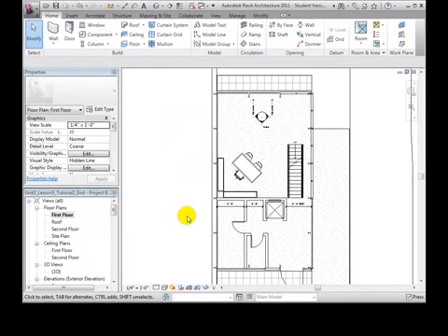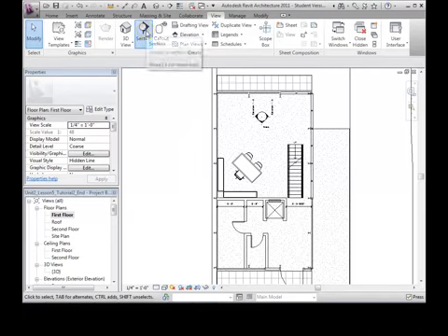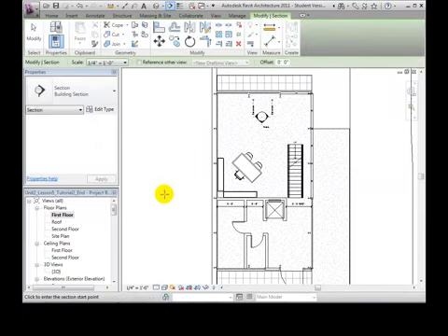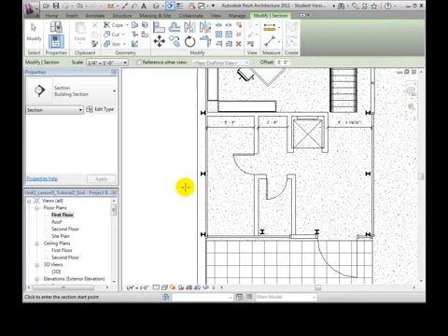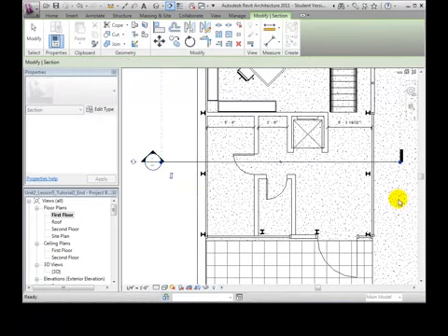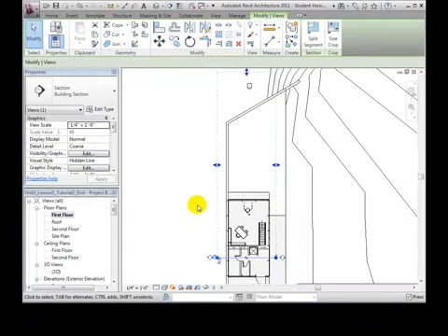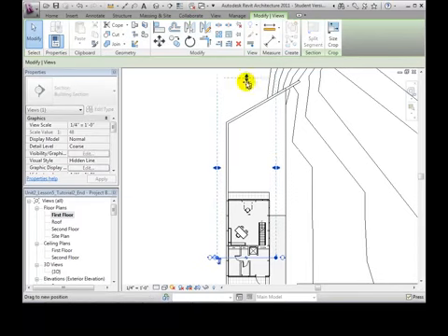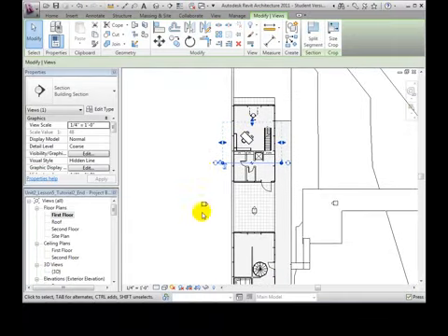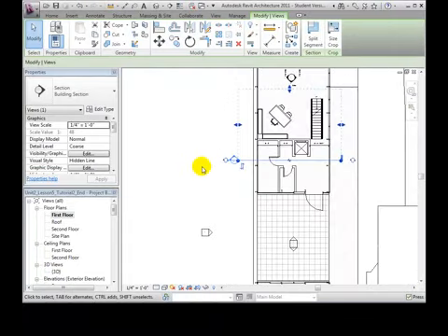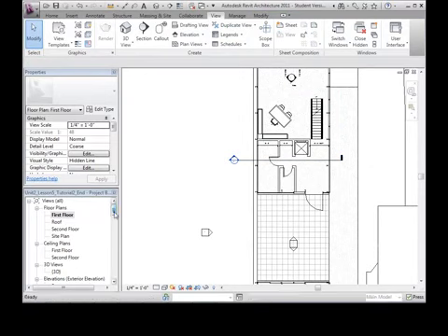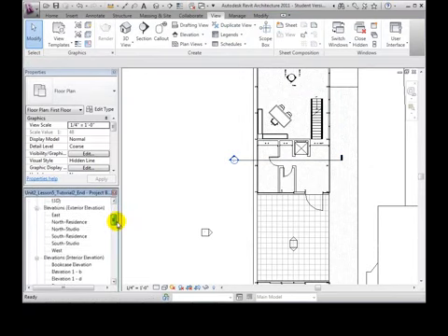In the View tab, open the Section tool. Now, let's draw a line where we want our view to be located. Next, let's adjust the far clip offset. Find the new section view under Sections in the project browser and open it to see what we have just created.